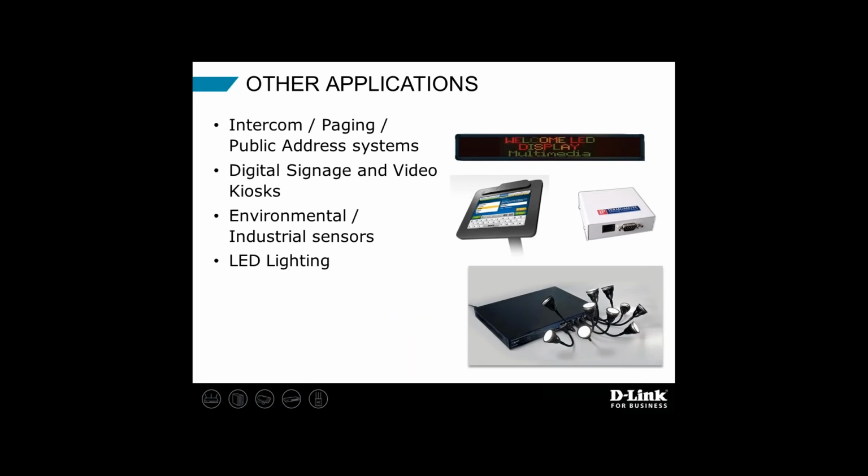A lot of other applications for PoE that we don't have time for. There's intercom and paging and public address systems. Certainly digital signage as we go from the AT to the new BT spec. There'll be more applications for signage and video kiosks. There are a lot of environmental and industrial sensors that you can get today that are PoE powered. And then, as I mentioned earlier, LED lighting is a new application that's coming fast and furious, and I see good things happening there.